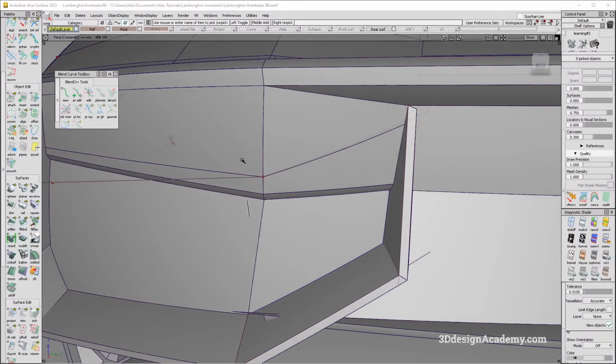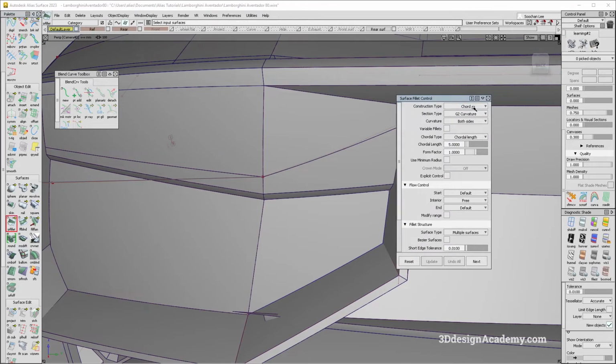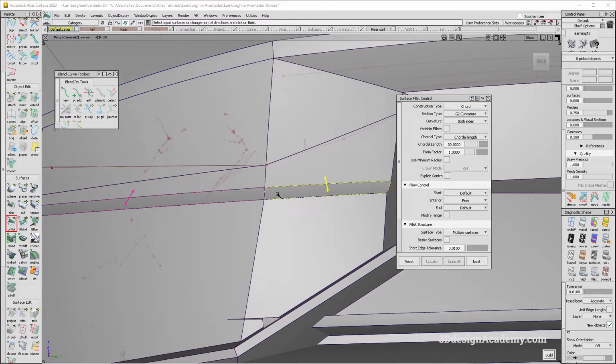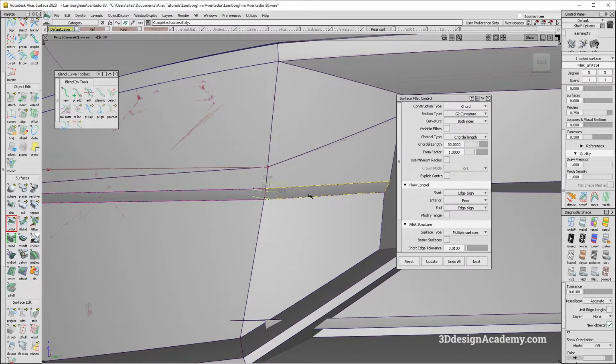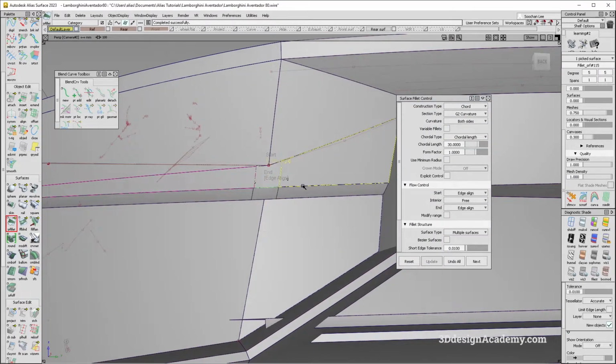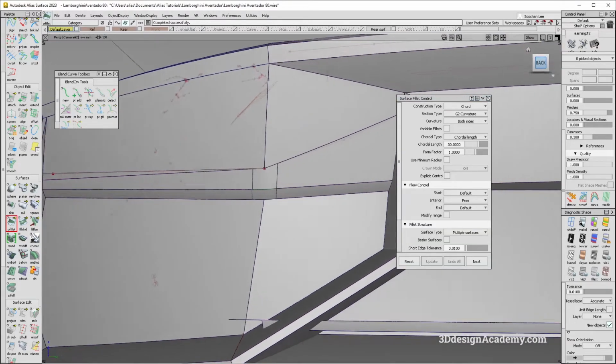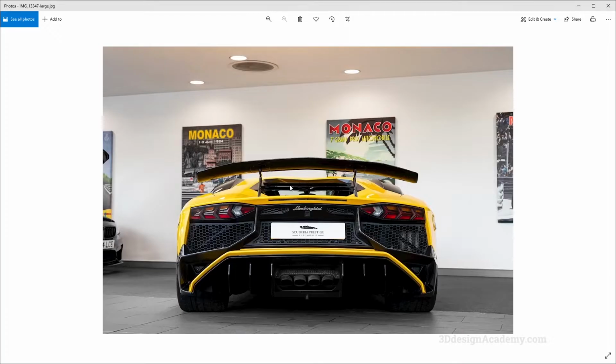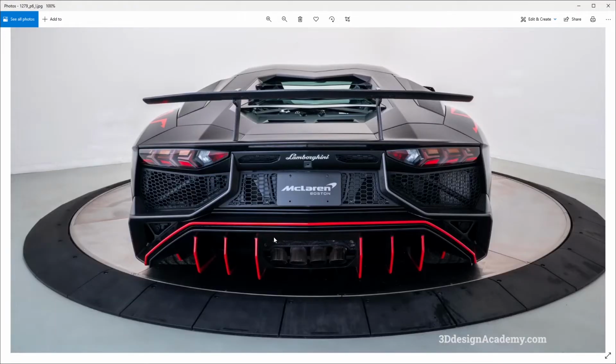Okay, so there needs to be a fillet here. So I'm going to say curve G2. Let's start with something a little bigger. Well, maybe not 50, maybe start with 30. And let's just put that in. So it's going to be edge line on both sides. Like this, edge line here and here. Now, it does look like it needs to be a lot bigger, even just looking at this image. So let's go ahead and put that in.